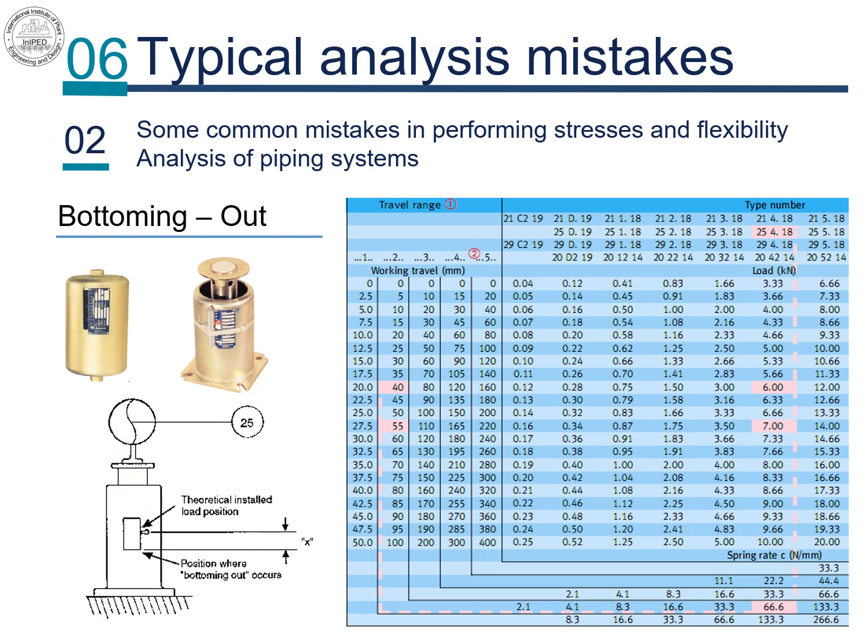When the pipe is in operating situation, it will move down according to the analysis, for 15 mm, and the spring will be further compressed, to 7 kN. On the spring travel scale, this will be at the travel position of the spring at 55 mm from 0. We see on the working travel range that the selected spring will have another 45 mm of travel, which is actually a safety margin, before it reaches 100 mm of travel and bottoming out. So the total travel before bottoming out from installed position will be 60 mm. The pipe stress analyst should ensure that in all operating regimes, pipe travel with this spring will never exceed this distance.